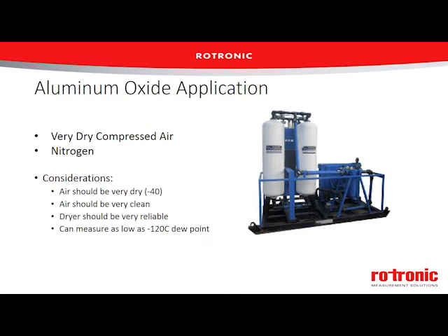But anytime your air is not nice and clean and dry, chances are, for example, if you get condensation in the compressed air system, or the system where you're measuring gets on these sensors, the calibration goes very fast. And then they have to be sent in for a recalibration, which is usually an expensive and long process. If the air is not clean, for example, if you've got compressed air that uses oil for cooling, then that oil can get on the sensor, it can cause a problem. So that's the type of applications that you can use them in.